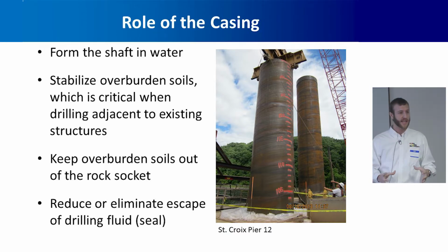We also want to seat the casing into the rock socket to keep any loose material from the soil over the rock from getting down into the socket. And we want to get a good seal into that rock so that we are not losing a bunch of drilling fluid into the overburden. And if we were in the scenario where we were going to try to dewater the hole, obviously we would need a good tight, watertight seal.